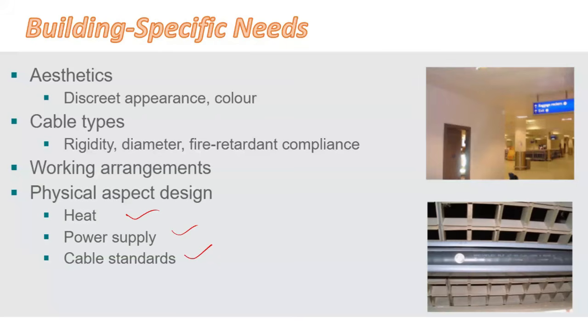As the building is going to be modified in certain ways, we should also communicate properly with the building owner and operator for their specific requirements. For example, a very critical aspect can be where to put the antennas. What's the antenna location where we can put it? An RF expert may have some optimal solution for antennas to maximize the coverage, capacity, and quality. But building owners may not agree with such installation since it may affect the aesthetics or certain spaces, or it may be difficult to install antennas there, right? So compromise should always be made between owner, operator, and the building and the DAS installers, right?